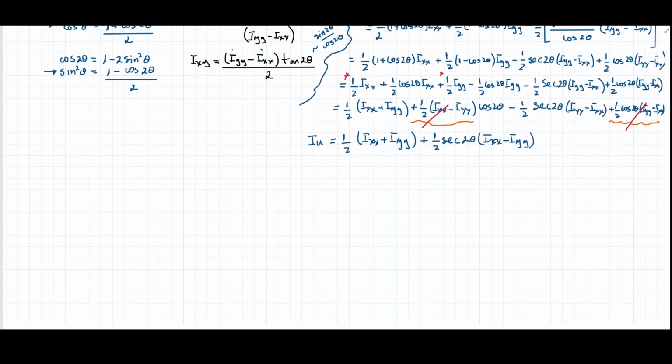Then we found the value of the second moment of area around the U axis, which is the principal axis, by using known terms like the moment of inertia around the Y and X axes. And we have just got rid of the product of inertia, the product second moment of area. Let me mark it down with some sort of indication that, okay, this is fine.